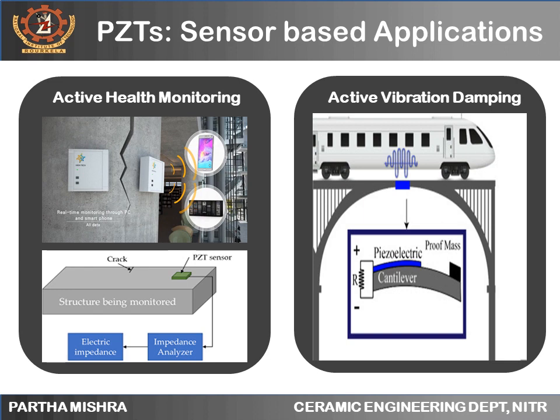Since we generally use connectors such as bolts and nuts in construction of bridges and trains, now these connection elements may loosen or develop cracks due to external impact caused by the movement of the locomotives. And if it is not monitored regularly, it may lead to unannounced and catastrophic disasters. Also, it's not feasible to monitor it manually every hour and so. So these piezoelectric sensors, which can produce reasonable accuracy and are suitable materials for structural restoration compared to other conventional materials here, as they are lightweight as well.